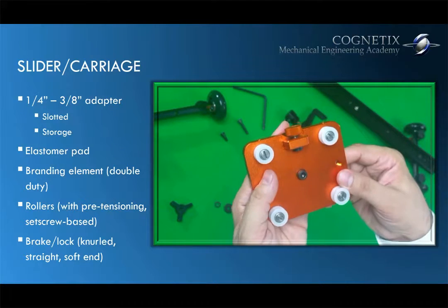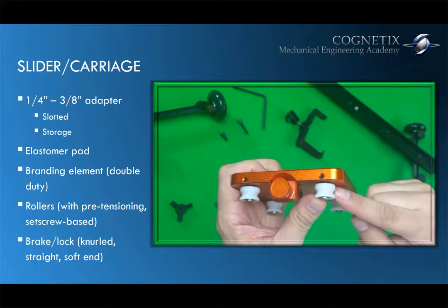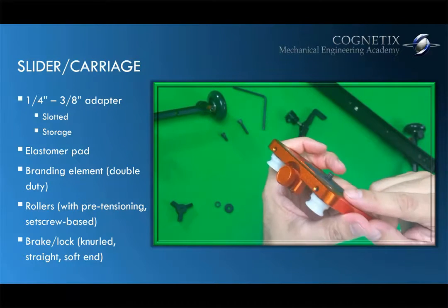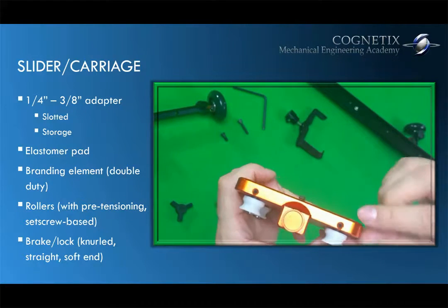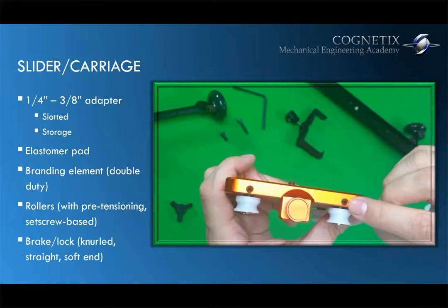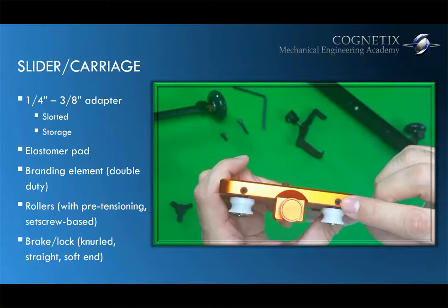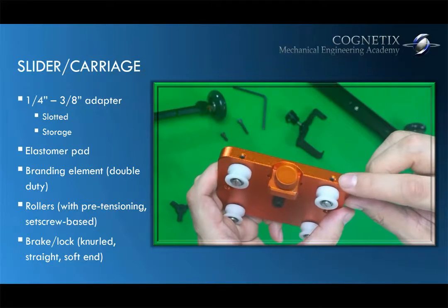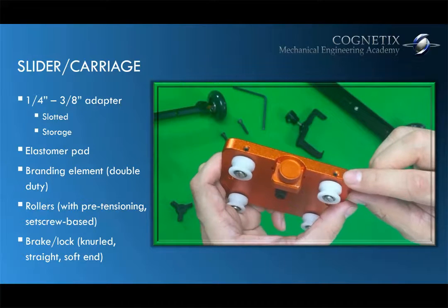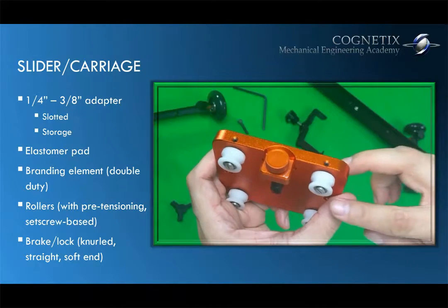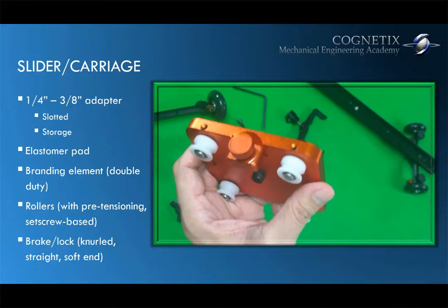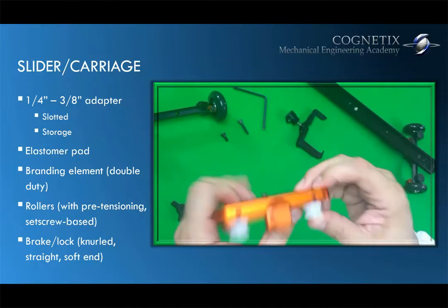Okay, I'm actually gonna go ahead and disassemble this because I want you to see a little bit more detail how this is done. You'll notice here holes that are for set screws. Okay, the set screws are what is used. It's the means that the designer chose to bring the axis closer to the rail. So let's go ahead and take that apart for a moment.